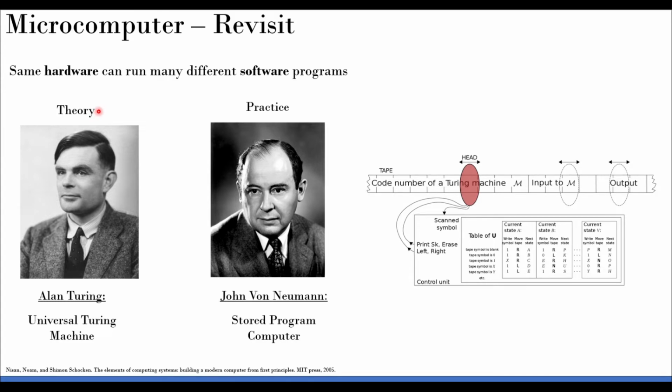So this was the concept Alan Turing introduced, and later it became practical through this great person, John von Neumann. That is what we call the Neumann architecture. Hopefully all of you remember what is Neumann and what is Harvard architecture. If not, please always remember that. Neumann means only one bus which carries both data and address. Harvard means you have two separate buses for data and address. So the concept Alan Turing proposed was put into practice by John von Neumann, and of course he called it a stored program computer. Okay, so this is the history. Those who are very interested, please do further search on this and get enlightened.